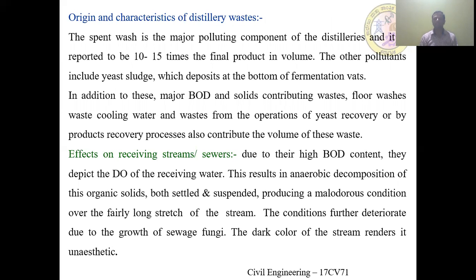What are the characteristics of distillery waste? The spent wash is a major polluting component of distilleries, and it is reported to be 10 to 15 times the final product in volume. Other pollutants include yeast sludge, which deposits at the bottom of fermentation vats.